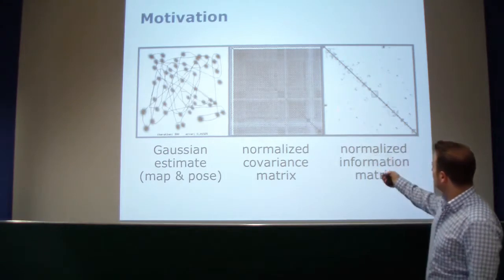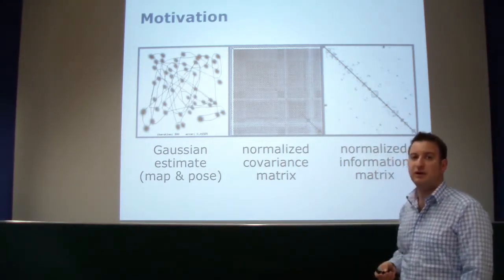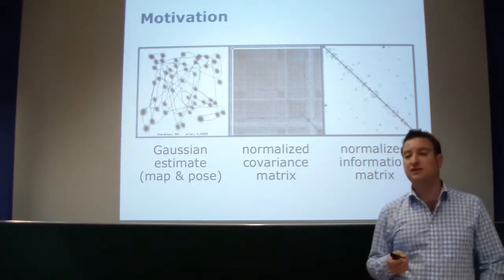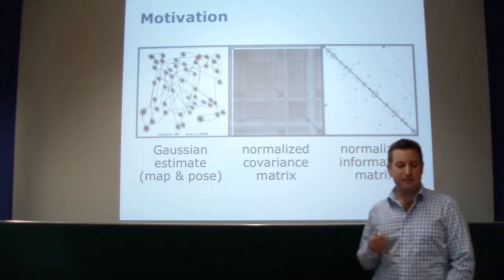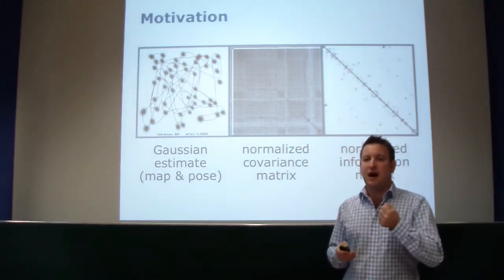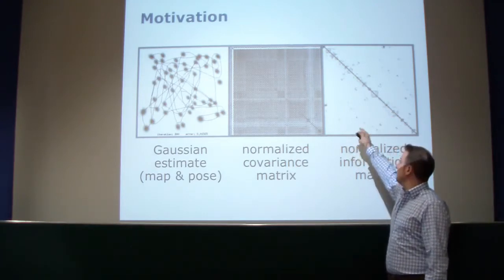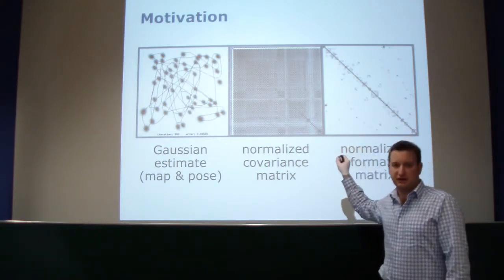But the key insight or the motivation for the SEIF was when looking into this information matrix part, and you can actually see that this information matrix is basically sparse, or has only very few values which are significant. However, in theory, what's not depicted here on the slide is that all these off-diagonal elements are close to 0, but they are not exactly 0.